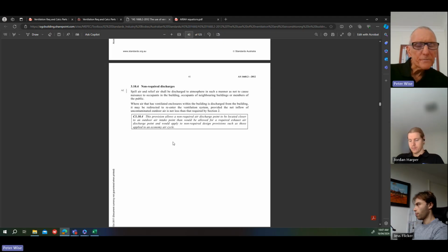So what it does is when you bring in outside air, to reduce the energy impact of the outside air, you exchange heat with an exhaust air stream from the space. And so you pre-cool and pre-dehumidify the incoming outside air.